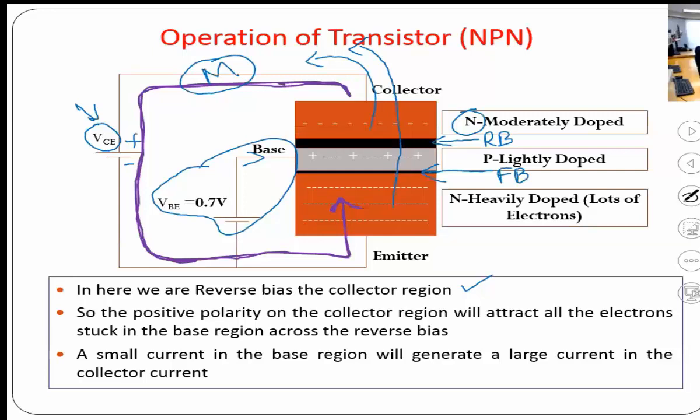Small voltage which gives you very small current, correct? Before you quit, it's two PN junctions. That means it's like two diodes back to back. It can be visualized like that, but you cannot make a transistor by simply taking two diodes, because in a diode the doping concentration is the same for p-type and n-type. Transistors can be visualized as two diodes back to back, but that doesn't mean I can make my own transistor from two diodes, because the internal doping concentrations are going to be different.